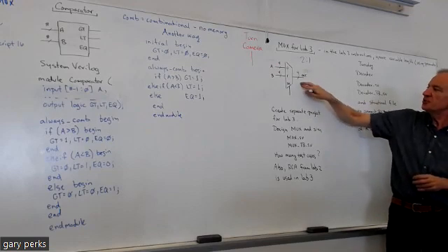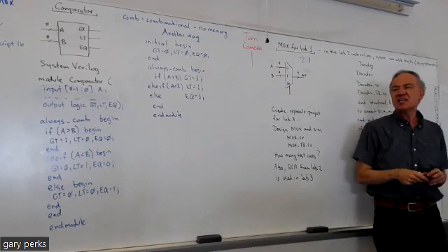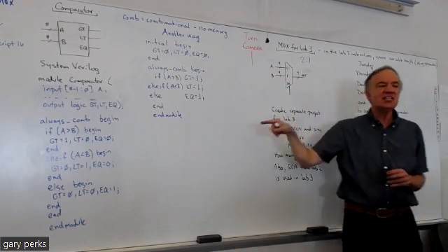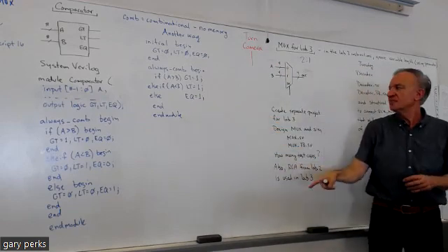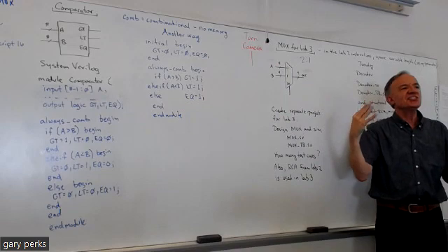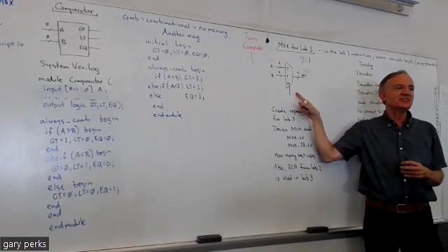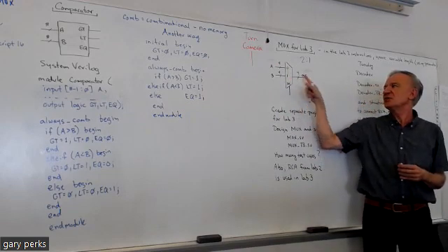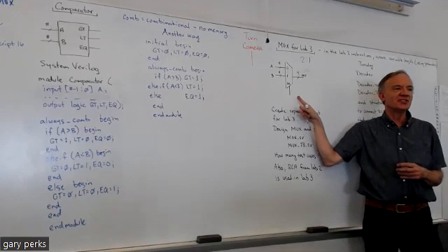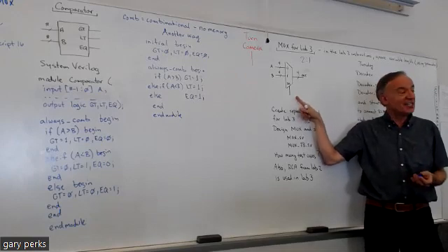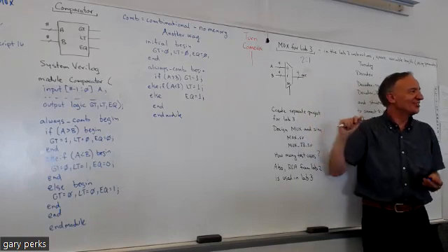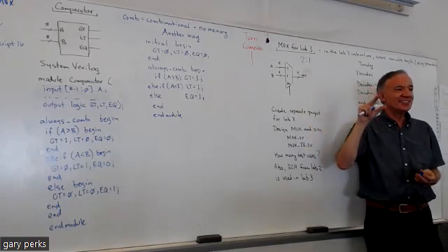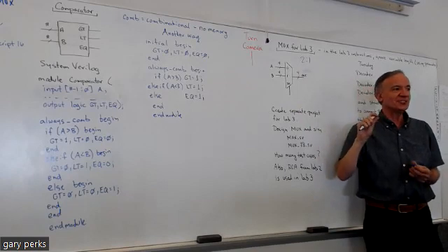Okay, so we want you to model this 2-to-1 mux using an if statement. And the if statement that you need is a lot simpler than that example. Because what's going to be the condition in your if statement? What's determining which input gets connected to the output? The select. So, if select this, output equals this. Else, output equals the other. And you see it's a simple if statement.